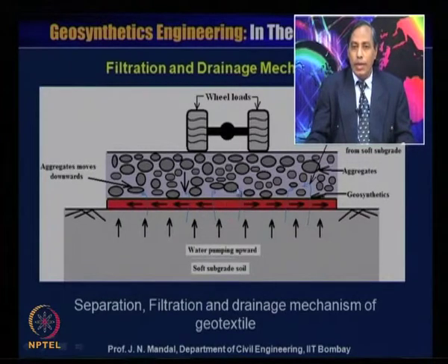You can see that the geosynthetic material acts as a filtration, and at the same time as a drainage. It also separates the coarser and the finer material, and that is why it acts as a separation. Also, due to the load, there is a deformation of the geosynthetic material, and then it also acts as a reinforcement. So all these functions happen at a time, and that is called multifunction.